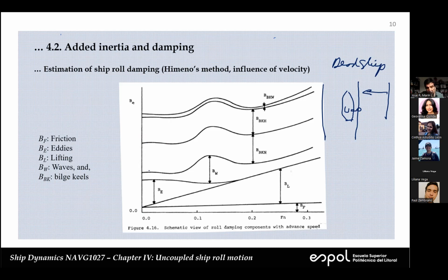That's why they call it dead ship. That situation occurs when, for some problem, we lose power, so the ship doesn't move. The waves start heading and basically push it from the side until you start receiving the waves from the beam. You lose power, the damping coefficient is reduced, and usually the waves push you so that you receive waves from the beam. So that's the worst.